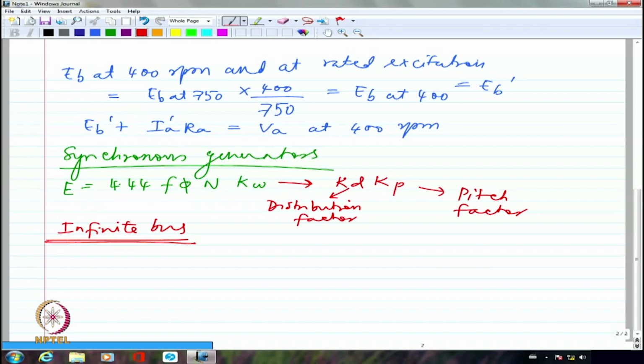If I say that it is 400 volts, what I am getting in my laboratory from the grid, it will remain by and large at 400 volts. It can deviate very, very little. Similarly, the frequency, if I say it is 50 hertz, it should remain at 50 hertz. The maximum deviation I may have is from 49.5 to 50.5.